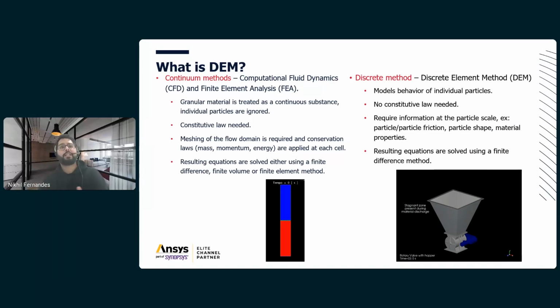But before we go into that, most of the structural simulations that you'll have heard of today, or fluid flows, are governed by a numerical technique called finite element analysis, or finite volume for fluids. These are either solved at the nodes or at the cell center, and that is what governs the solids and fluids as a continuum. However, the discrete element method is a Lagrangian method which basically tracks the particle motion by solving the equations that govern their rotation and translation movement.